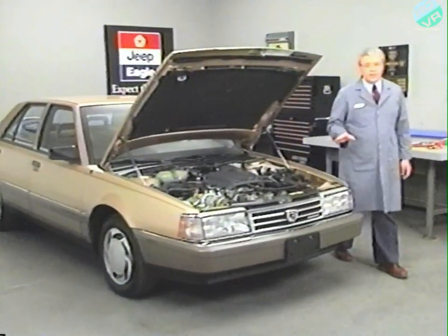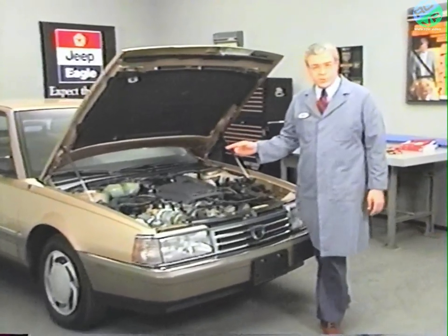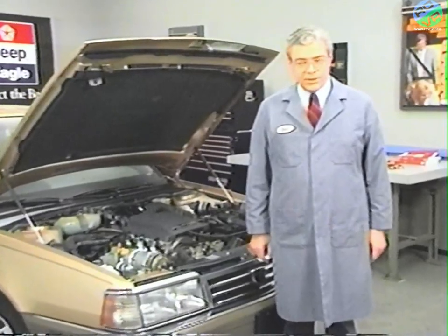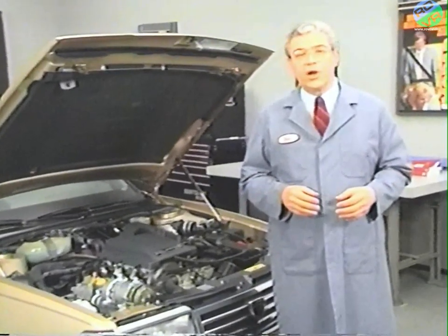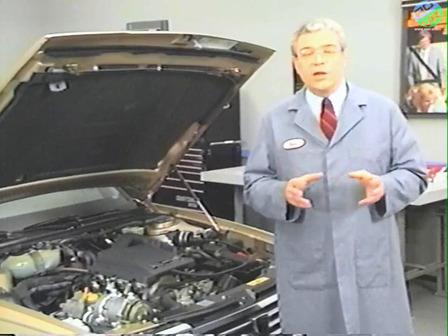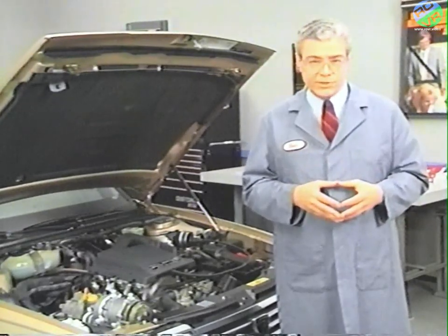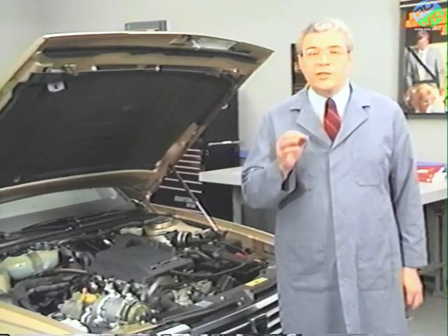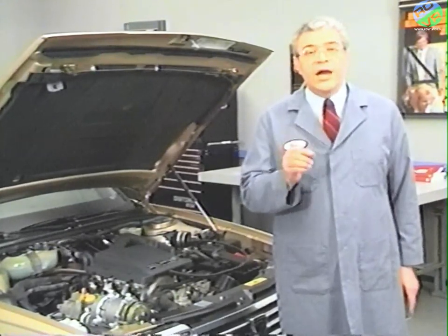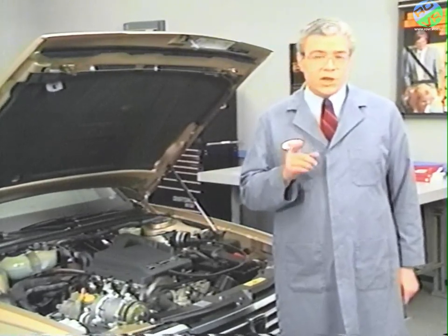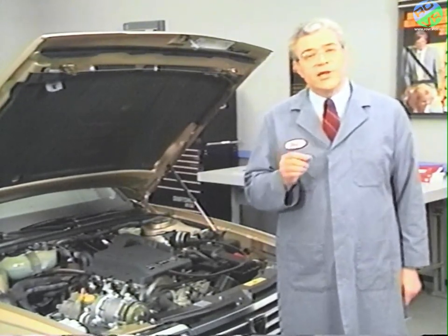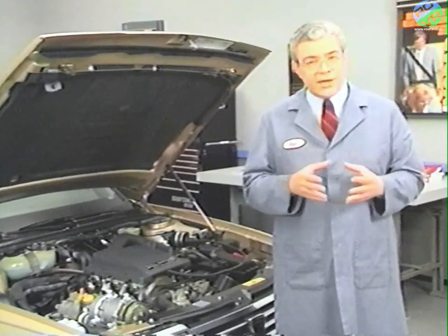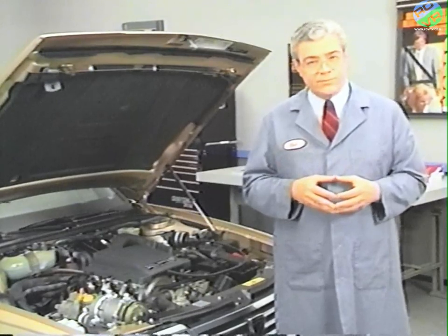It's important to keep in mind that the clutch cycling pressure switch is the only pressure-sensitive switch controlling AC operation. There is no expansion valve or high-pressure cutout switch to start or interrupt compressor clutch operation. The input to the ACM is strictly from the low side and depends on refrigerant pressure, not evaporator temperature. It's also important to keep in mind that ACM operation of the AC clutch relay depends on more than just the status of the clutch cycling pressure switch.